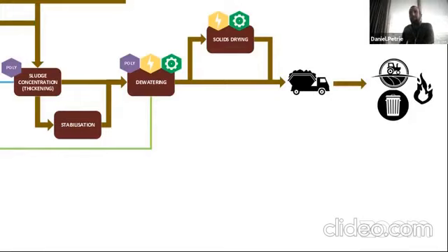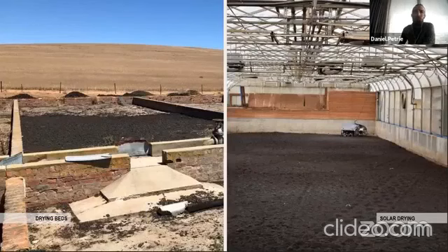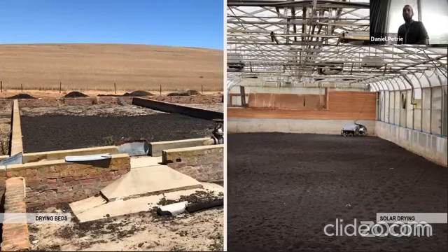It's the only way to sort of evaporate off the water, and that heat can either come from the sun in passive solar drying systems. So in South Africa, we have certain parts of the country that are really well suited to this, and down in the Western Cape for sure. Very affordable way of drying sludge. But other places where the precipitation in the year is too high and the humidity is too high, you might not get effective evaporation just by leaving it outside.